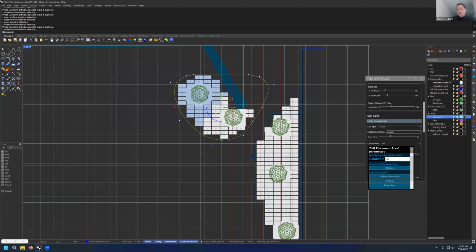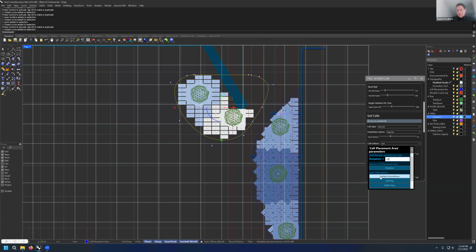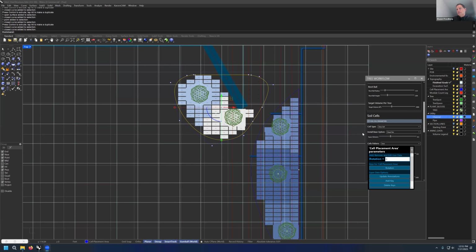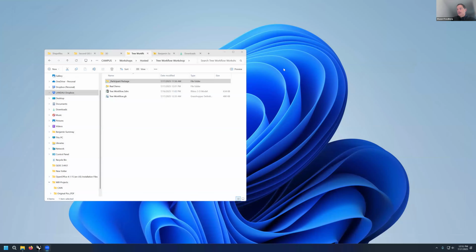If you're thinking about a 30-foot diameter canopy, where they're spaced 30 feet on center, the research suggests that 1,000 cubic feet of soil is the goal. 1,300, 1,400, 1,500 cubic feet is better, and you see some of our projects that have been worked on, actually going back to Chris at Olin a long time ago, like the Metropolitan Museum of Art or the Claude Cormier projects in Toronto, Sugar Beach, those are exceeding that in volume.